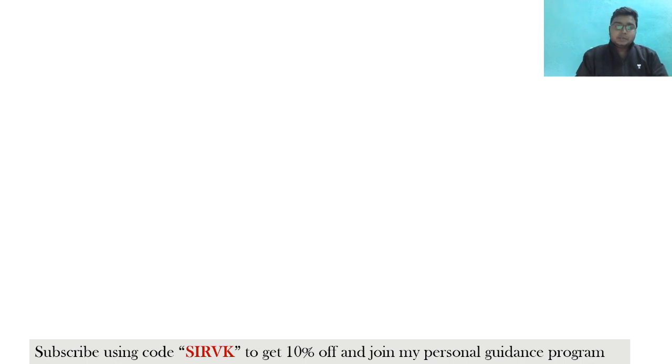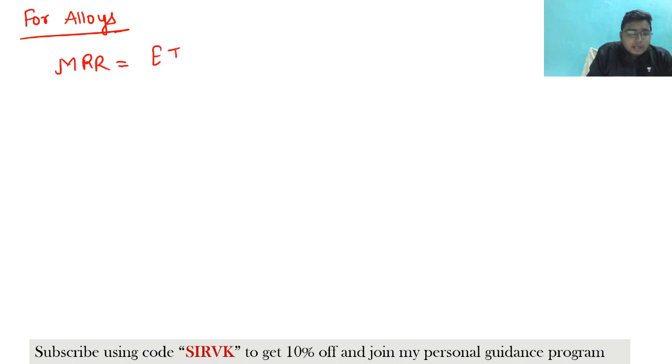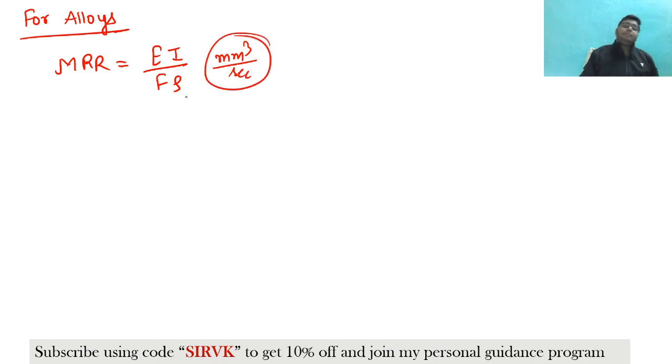So till now we have seen the processes for the material removal rate for the pure substances. When the material is pure, then we have this kind of material removal rate. Suppose let us find the material removal rate for alloys. Basically what we know is that MRR is actually EI by F rho, in mm cube per second. This is valid for a pure metal.